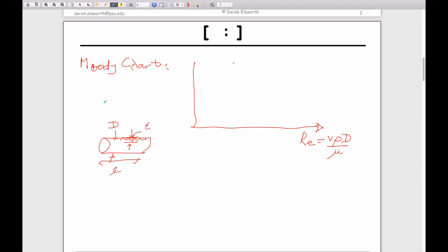And we know that the head loss universally in this expression is equal to some friction factor, a scaling of how long the pipe is relative to its diameter. Clearly, if you double the length of the pipe, all things being equal, you double the resistance. You quadruple the length of the pipe, you quadruple the resistance. Hence, that would change. And it scales with the velocity at which it's flowing. So this Moody chart, of course, gives friction factor as a function of these behaviors.